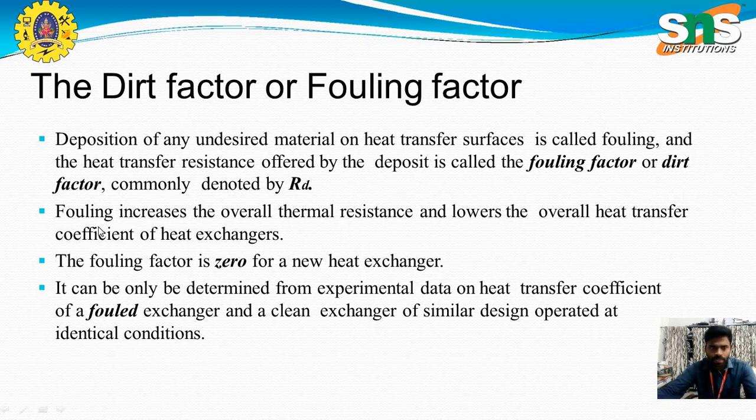The second point, the fouling increases the overall thermal resistance. Yes, if we want to transfer heat energy, this fouling will act as a resistance, and it increases the overall thermal resistance to the heat flow, and then lowers the overall heat transfer coefficient for the heat exchanger.